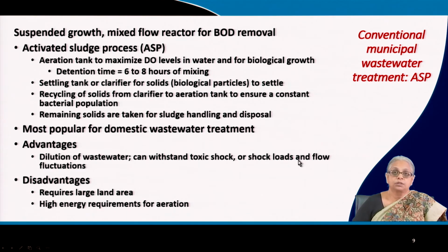Similarly, you may have shock loads in terms of volume of the water to be treated. For example, there are daily variations, there are seasonal variations, there may be huge amounts of water released from certain activities within the city. All these things can contribute to shock loading and flow fluctuations, which are either daily or seasonal. So all these kinds of changes, which are either instantaneous or even over a slightly longer period, all this will contribute to upsetting any process.